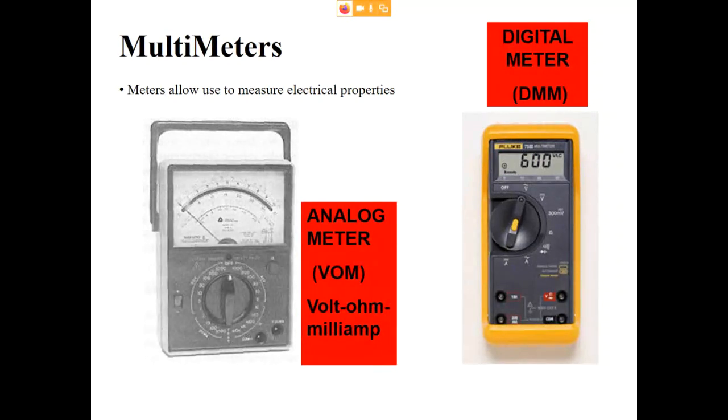Okay, so you need to be very careful when you're trying to measure currents and voltages that you're hooking the meter up correctly. And you physically have to rewire the connection into the meter to measure either a voltage or a current. All right, and I'll do a video on that later, and we'll discuss that when we're actually in the classroom. To measure a resistance, you need to make sure there's no power applied to the circuit, and you need to disconnect the circuit from the power supply.